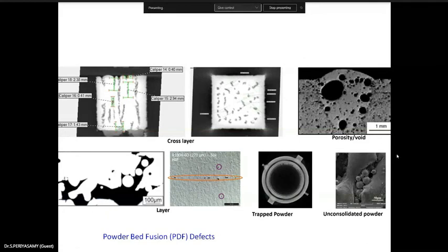Here, for nickel alloy, you have the ASTM F3050 standard. Similarly, if you are going for titanium 6 aluminum 4 vanadium, you have to go for ASTM F2924. Each one describes the procedure, what the built energy is, how to supply the part, then